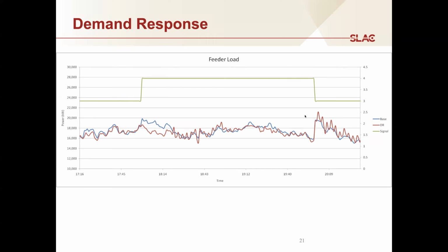So first of all, the takeaways on this kind of a study are there's really no benefit to holding the curtailment signal during this time, except to the extent that you can defer when this kind of rebound behavior will occur. So in this case, the initial response will be beneficial for peak load shedding, and then you basically hold the loads until you can absorb the rebound without adverse effect on the system.